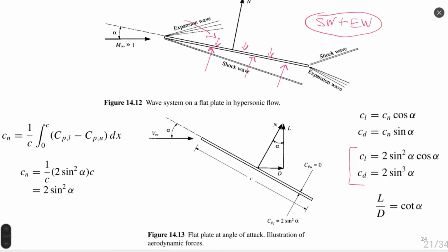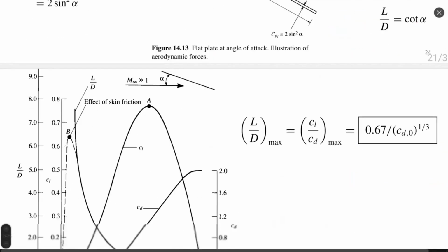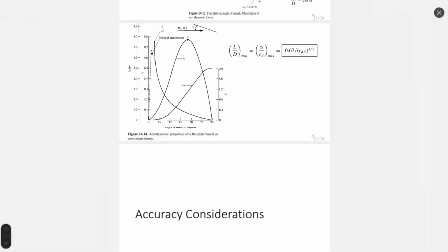But Newtonian theory is an approximation, which is not a solution of flow equations. So results between these two models will be different and will always exist. It's just for us to evaluate how much this difference would be. The closer we are to hypersonic flow, the smaller the difference would be, in my opinion. I think we have such a comparison here.